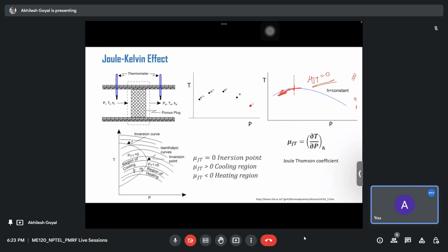So in this region, the Joule Thomson coefficient is positive. That means in this region, if we drop the pressure using porous plug or capillary action, then always the cooling effect will be achieved. But on this side, only heating will be achieved. Okay, and this phenomenon can be seen here in the figure. Here you can see for multiple initial conditions we achieved multiple graphs.